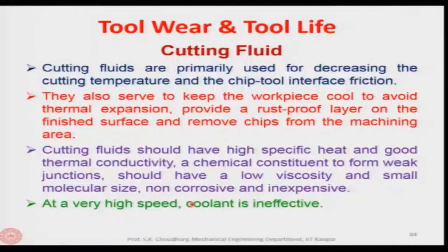At a very high speed, coolant is inefficient, because it cannot get enough time to reach the machining zone, and also it cannot get into the machining zone because of the wedge which is formed by the tool, the workpiece and the chip.